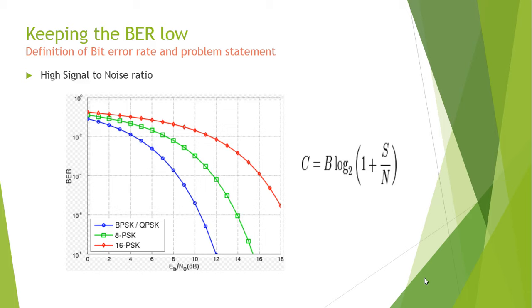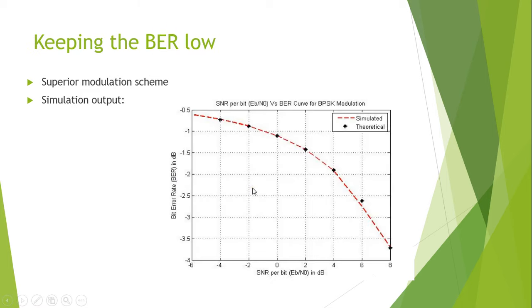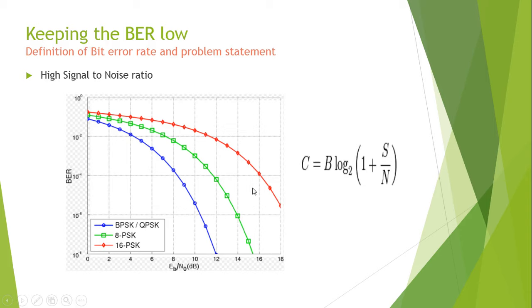We'll talk about signal strength first. So, we can see that in order to maintain a low BER, the Eb/N0 should be really high. The Shannon-Hartley capacity theorem for wireless systems states that data can be transmitted at a rate R which is less than C, where R is the rate and C is the channel capacity in bits per second.